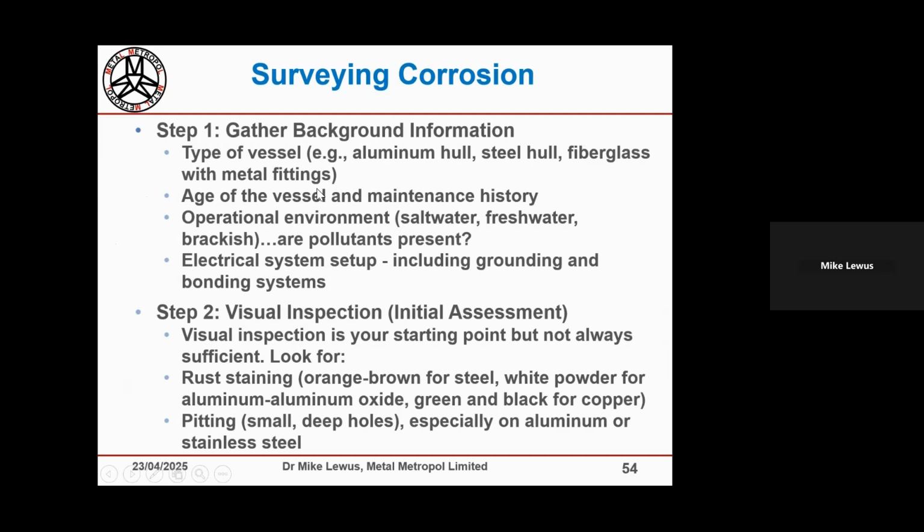You might have your own ideas on this sort of scheme, but certainly gathering background information: the type of vessel, the nature of the hull is pretty critical, the age and frequency of use, anything you can get about the nature of the water that the boat's sat in, the electrical setup. Some of these things are going to be problematic from the start because nobody usually knows what's in the water, and it can be quite expensive finding out. Anyhow, collect as much information as you can.